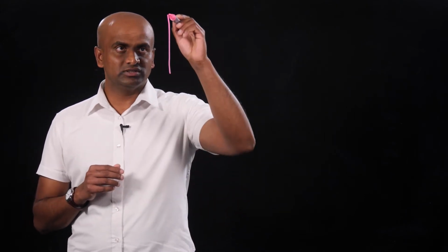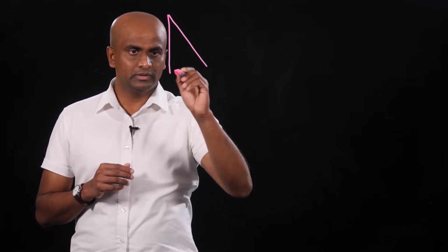So now in this part, since the channel is empty, there is no force acting opposite to the pore water pressure, or the pressure that comes from the water within the tension crack. Therefore, in this case, we need to consider the water pressure from the tension crack. So the tension crack is the CD part. If you have a tension crack like that, and it is filled with water, the water pressure varies linearly.